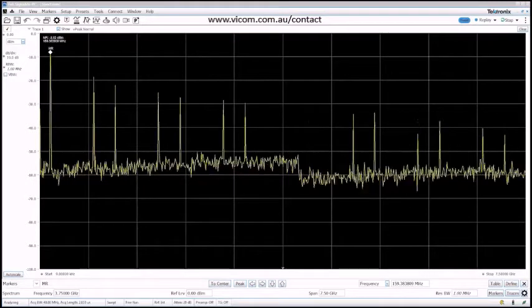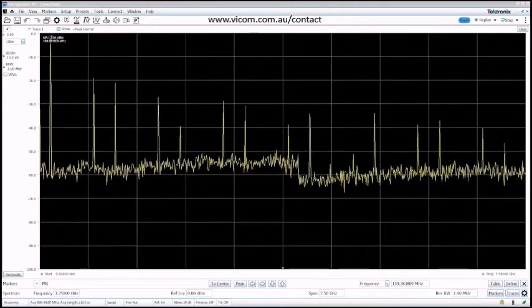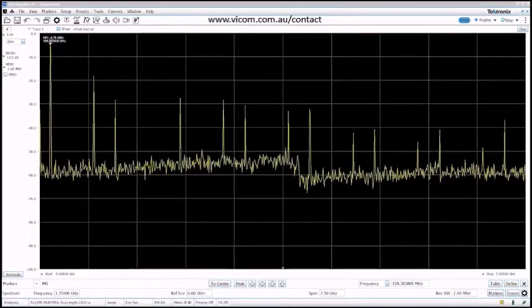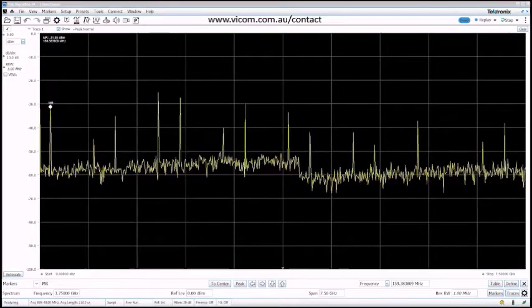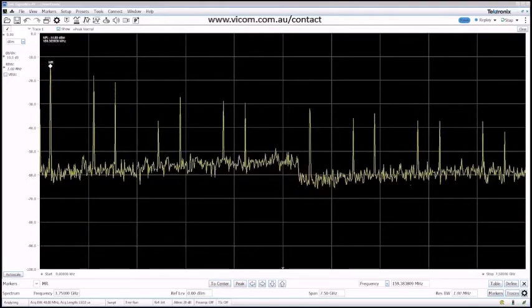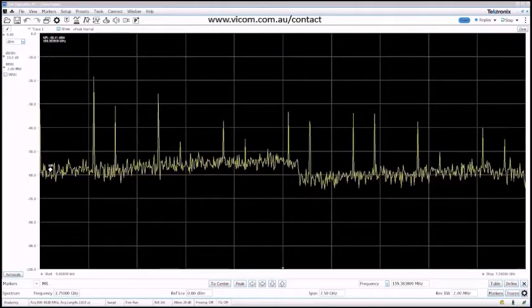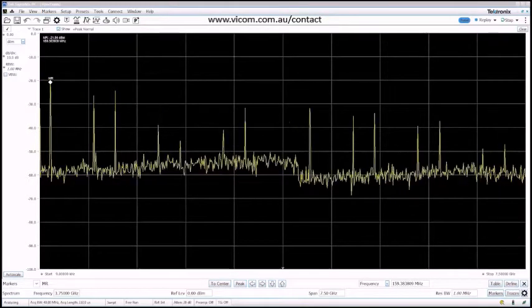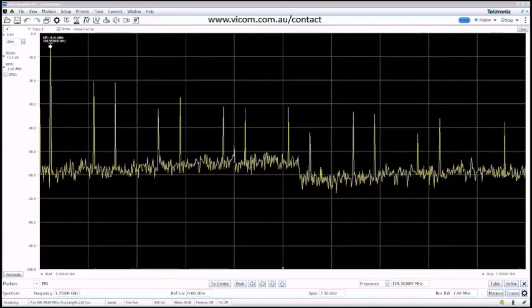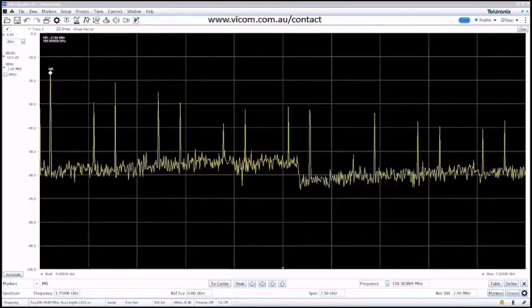Spectrum analysis, or analyzing a signal in terms of amplitude versus frequency, has historically been the basis for many measurements made by RF engineers and is still widely used today. You can measure signal power, harmonics, occupied bandwidth, and channel power. And if you know what you're looking for, you can pick out input-related spurious signals, measure amplifier compression points, and characterize third-order intermodulation products.